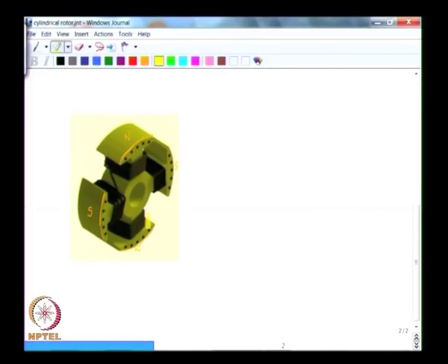Some flow of current is given through these windings, because of which this may generate a north pole, south pole, and so on. And this structure is then rotated so that the field that is generated bodily rotates along with the rotor. The field is again a DC field excitation, just like in the case of a cylindrical rotor arrangement.